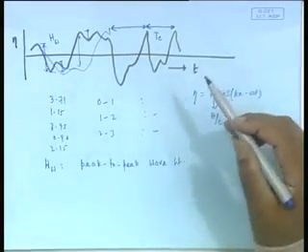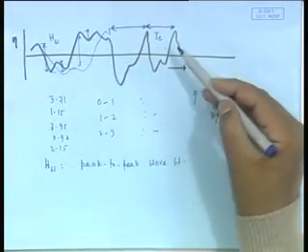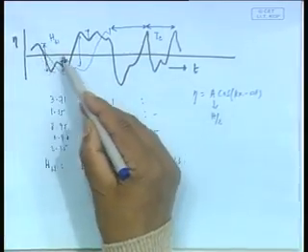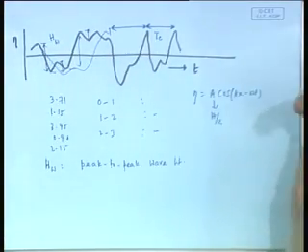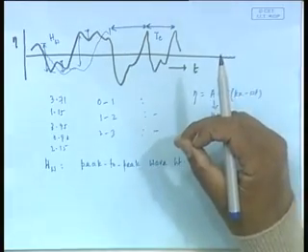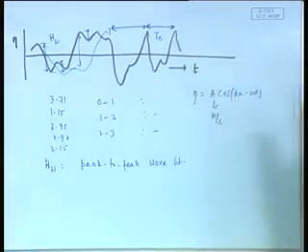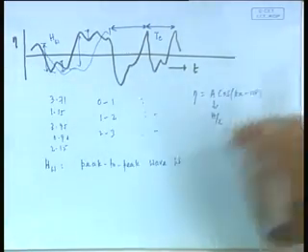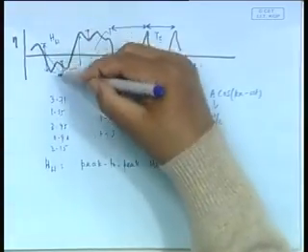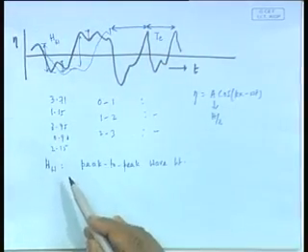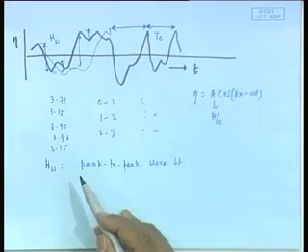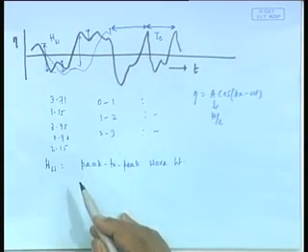But in an irregular signal, what happened? This mean level is not known. You do not see it. You put a record, you are only going to find this graph, you do not actually find this black line. The mean level is not known generally. That is why it is a convention to use peak to peak, because you do not have the mean level from which you are drawing this line. All you are getting is a record of this black line. That is why in random signals you normally use peak to peak. You do not use amplitude but height.